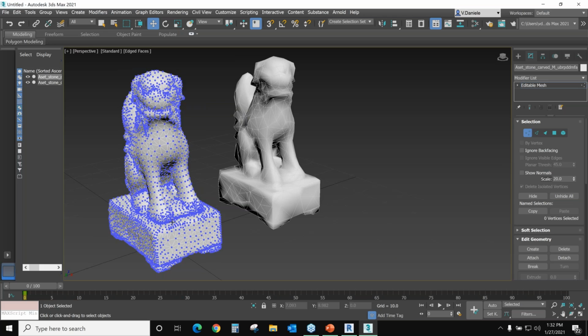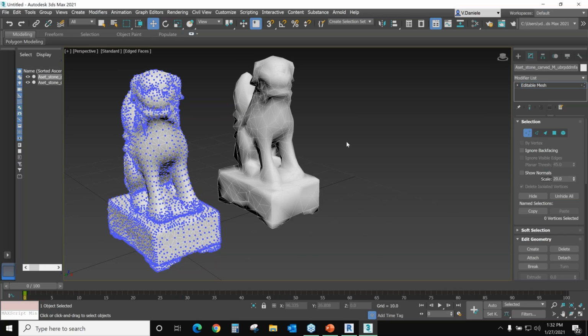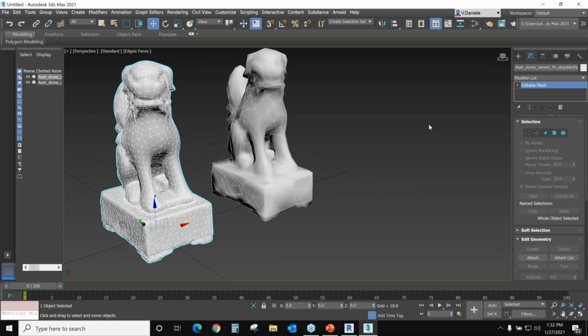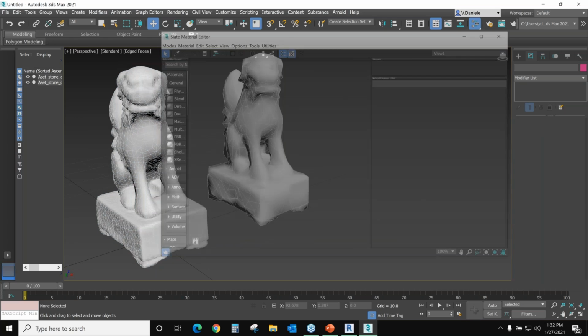So whatever program you're using, like 3DF Zephyr to create photogrammetry, if you have access to a program like 3ds Max, then we can use ProOptimizer modifiers to make the mesh less dense and to make it more performance enhanced. Now, with that, there are some tricks we can always get away with in visualization without having something this dense. We can always tie in a nice material.